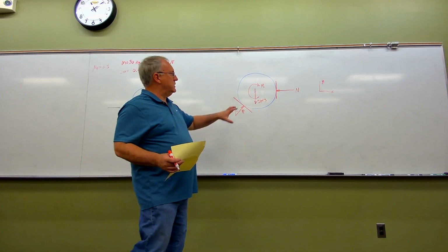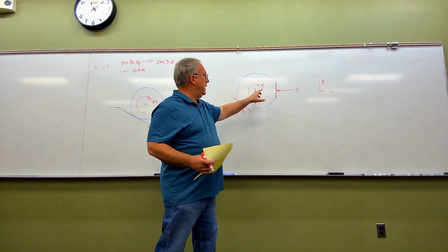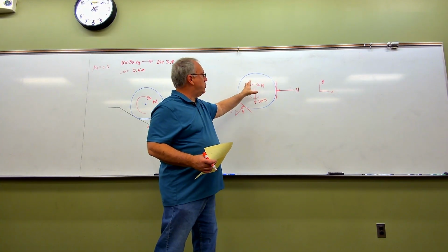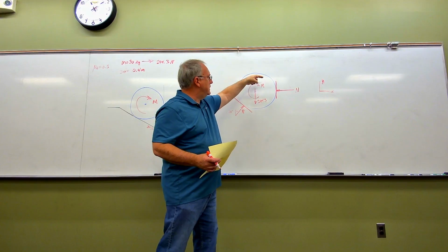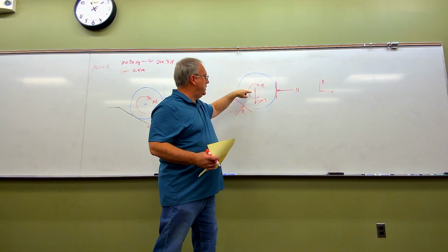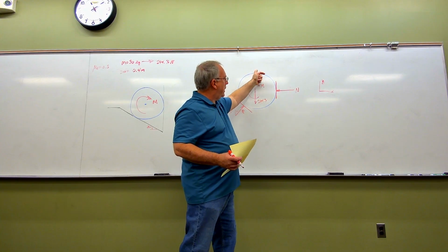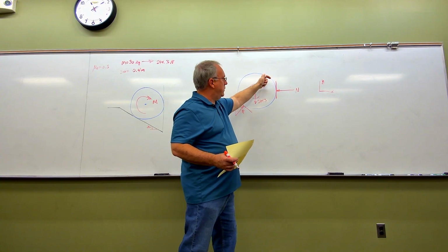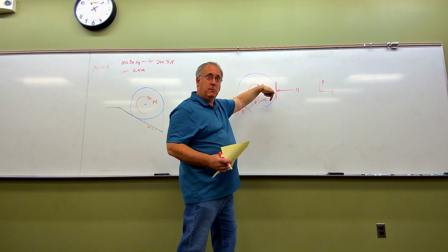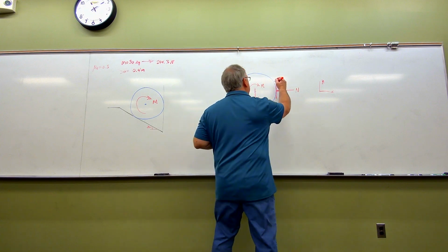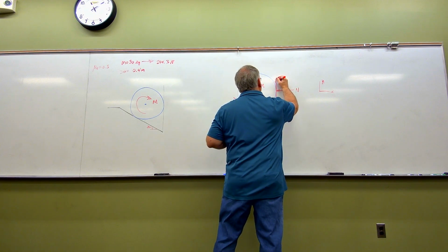So if you really did have a cylinder here and you're applying a torque that's trying to rotate this cylinder in a clockwise fashion, that means this cylinder's edge is going to try to go clockwise, going this direction. So if that's the impending motion, then opposing the impending motion must have an arrowhead up here.